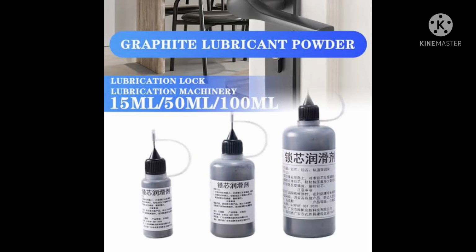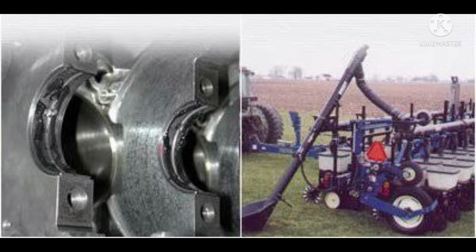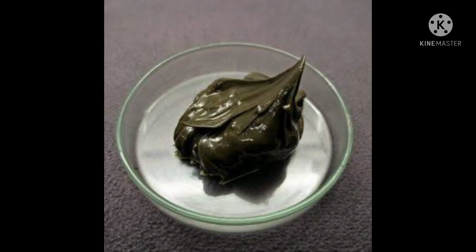Now let's discuss the uses of graphite. Due to its softness, powdered graphite is used as a lubricant for the fast moving parts of machinery. Since graphite is non-volatile, it can be used as a lubricant for the parts of machinery which operate at very high temperature. It can be used as a dry lubricant, or mixed with petroleum to form graphite grease. Graphite powder can also be mixed with lubricating oils.